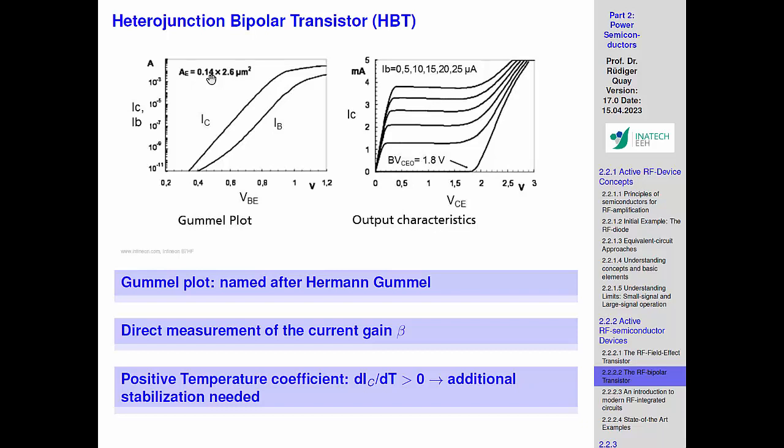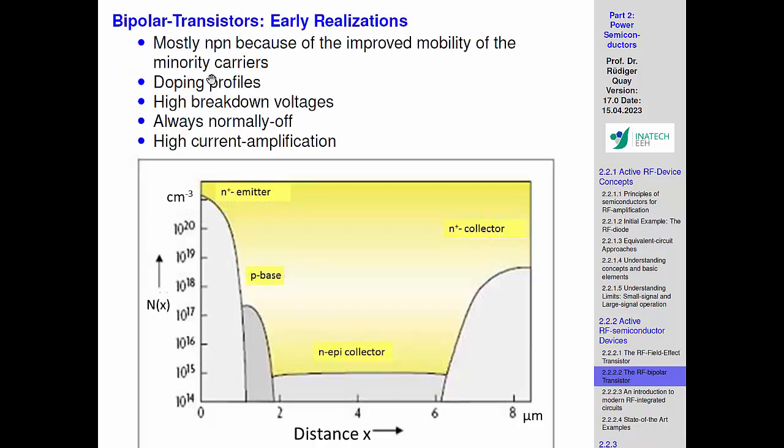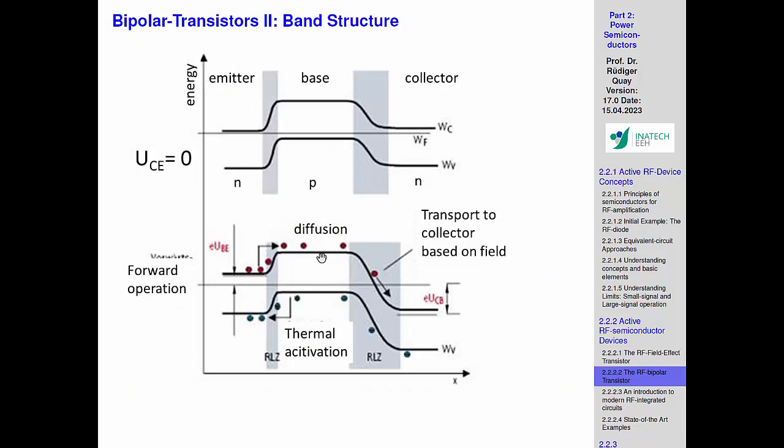You can, of course, argue a tablet is nicer than a cell phone, but it gives you a flavor of the point, because you can get the same transconductance also with a FET, but you need a lot more area. So that's why, and the reason is that this bipolar principle, which we just talked about here, is a really efficient physical drive. So it helps a lot to use this second current creating mechanism.